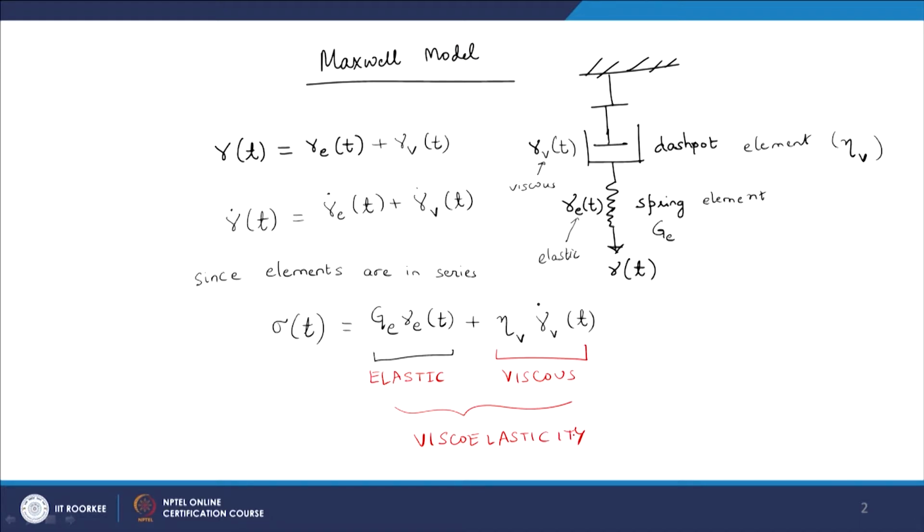It is a very simple model, but since we have incorporated an elastic element and a viscous element, this would also possess an elastic behavior and viscous behavior, and we will see how this model, that is coming from rather phenomenological origins with nothing to do with the polymer system, gives you a good representation of what actually happens if I do experiments on viscoelastic materials.